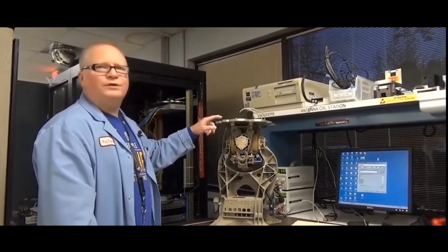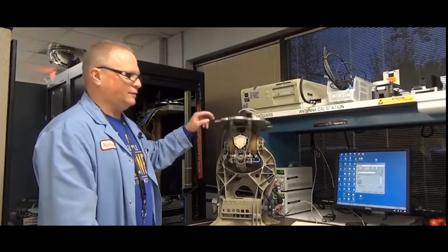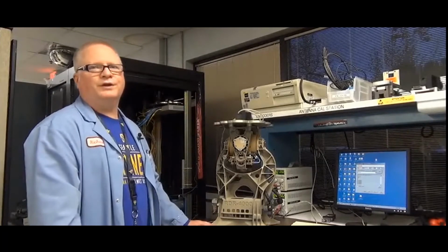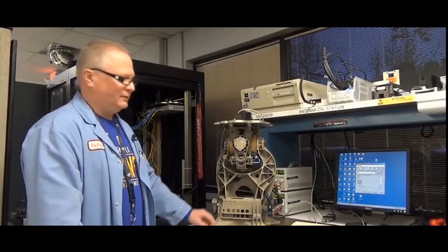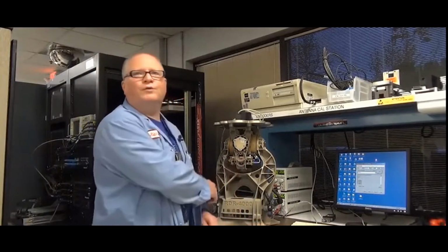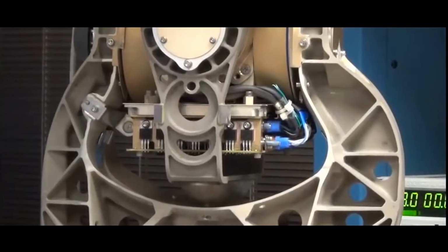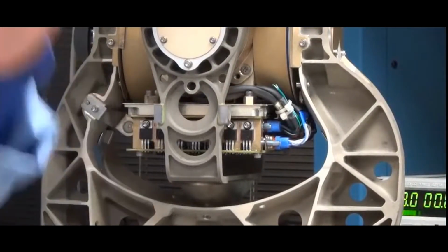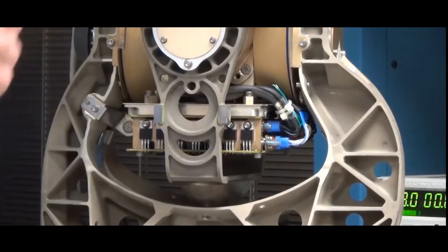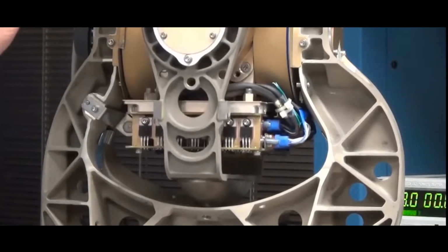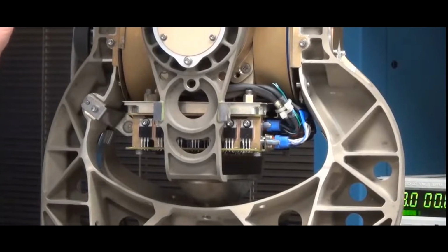On this one, you can see that there's very little resistance in your azimuth, and this is also an indication that you have a problem with resolver feedback. To verify this, we're going to want to get a close-up on this point right here. We're going to take a non-conductive stick or some type of object that doesn't have a sharp point on it, so we do not damage the equipment, and gently manipulate the wires and the rubber stop and the end of the connectors. And if you see the antenna gimbal move off the center on its own, not from pushing it, you're losing one of your resolver signals. There's a break in the connection, and that's also an indication that you have a bad resolver pin.